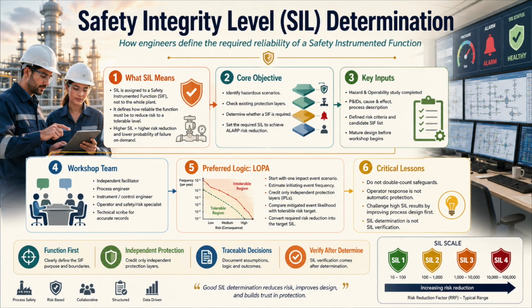Before allocating risk reduction to a safety instrumented system, consider inherently safer design, inventory reduction, lower operating pressure, physical separation, mechanical protection, relief systems, process redesign, passive barriers, and other technologies. A safety instrumented function should not become the default answer to every unacceptable risk. Instrumented protection introduces life cycle obligations, independence, architecture, diagnostics, validation, proof testing, bypass control, maintenance competence, management of change, and periodic functional safety assessment. The principal determination methods are layer of protection analysis, calibrated risk matrices, and risk graphs.